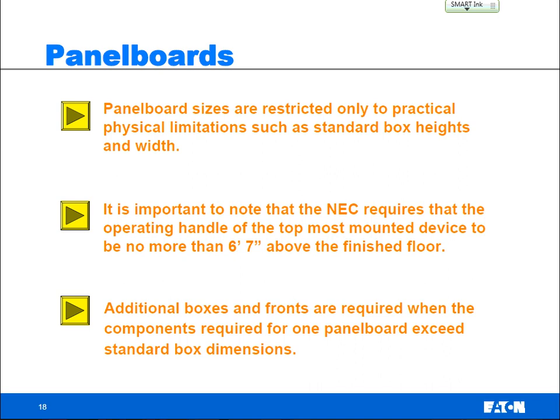When you talk 84 circuit panel boards, for example, those are pretty tall. Those are 90 inches tall. And when we design as a manufacturer, we might assume on a big panel board like that, you have to put the bottom on the ground or ground level. And if you raise it up by a foot, all of a sudden the top breaker is out of tolerance and you're going to get red flagged. So it's probably another reason why you don't see those larger panel boards a lot. And from a contractor standpoint, something you always need to be aware of.